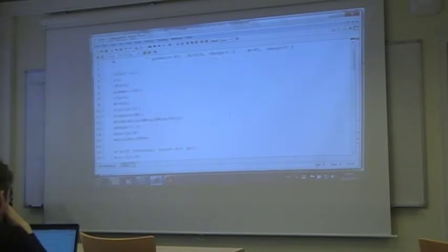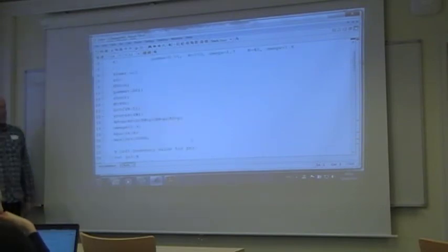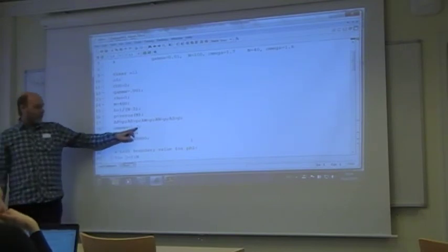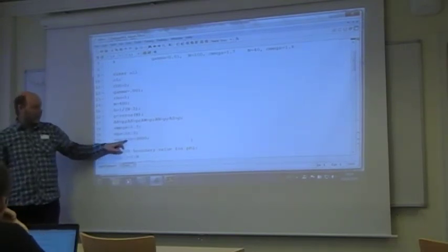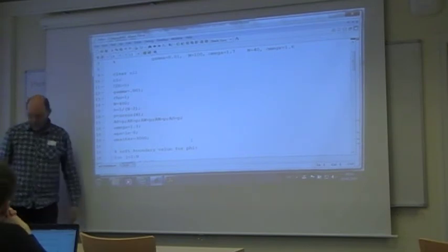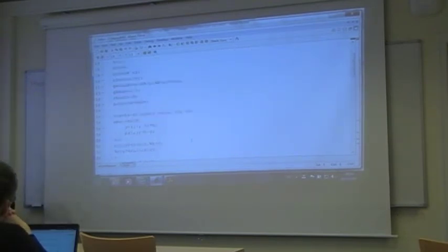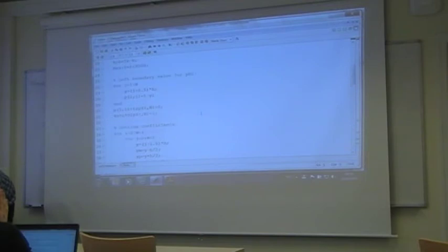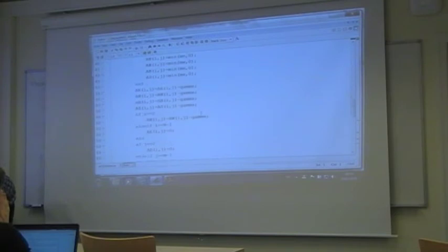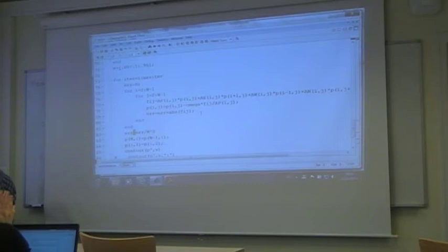So here it's possible to play around with this one as you like. I use an SOR here, so I play around with an omega and also the maximum number of iterations. And for finding the solution, I just choose an epsilon. Here, setting the boundary conditions, and then solving the equation system, just following the recipe directly.